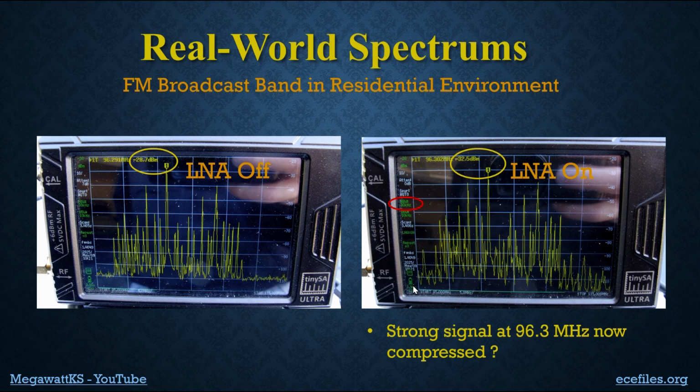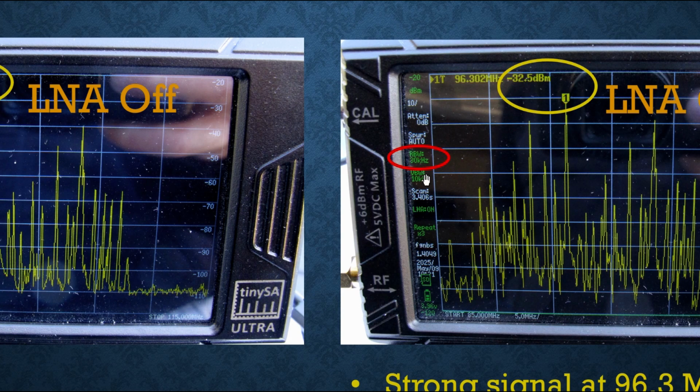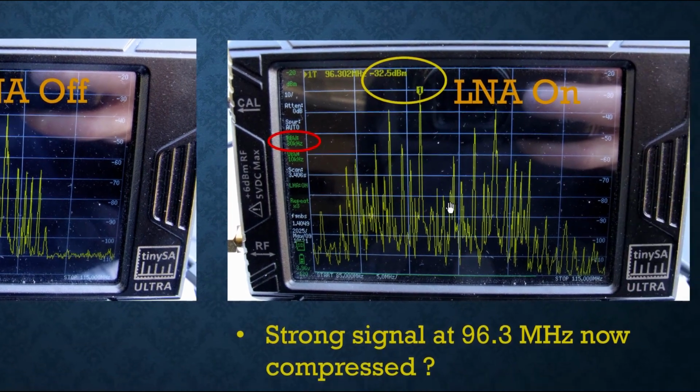When you're taking measurements like this, the resolution bandwidth here was set at 30 kilohertz. And this is FM broadcast, and FM broadcast signals are moving back and forth by as much as 75 kilohertz. So this amplitude will change over time. You'll see it bouncing up and down. This is a static captured picture, but it will move up and down. So it's quite possible that this wasn't actually -32 dBm, maybe just when this picture was taken. That's why I said here, strong signal, now compressed, question mark?